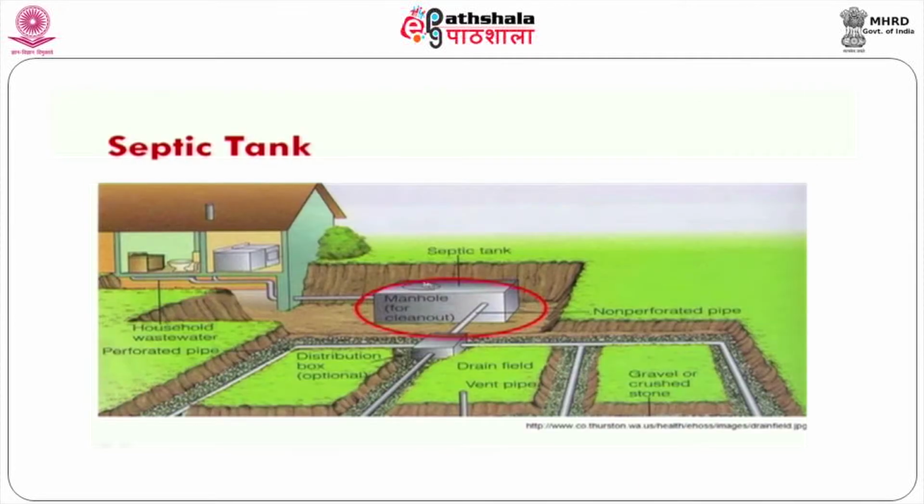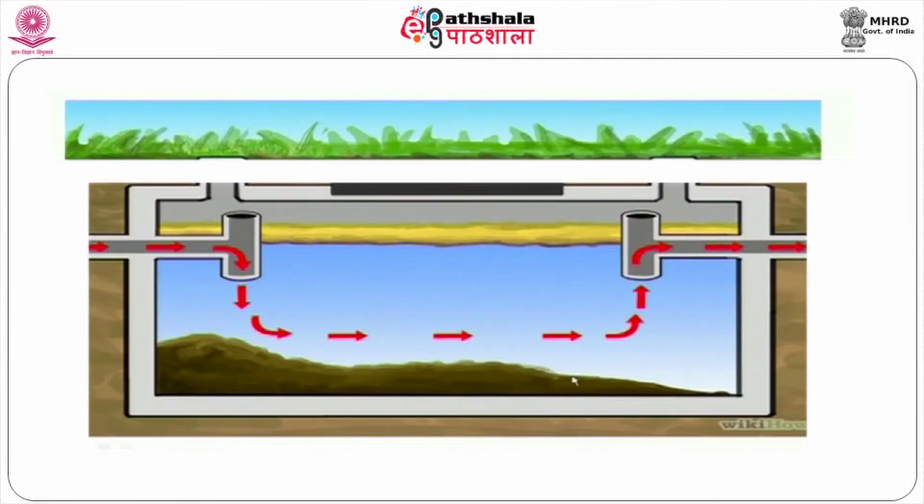This is another setup we have. Wastewater is collected from the septic tank into a holding chamber and finally dispersed into the dispersion field through drain lines like this. Here we have PVC pipes with perforations, or it can be stoneware pipe without joints. In order to disperse effluent evenly throughout the soil, the entire setup is embedded in a gravel pack assembly. So, gravel, perforated pipe and gravel pack are there. This is the configuration of a septic tank.